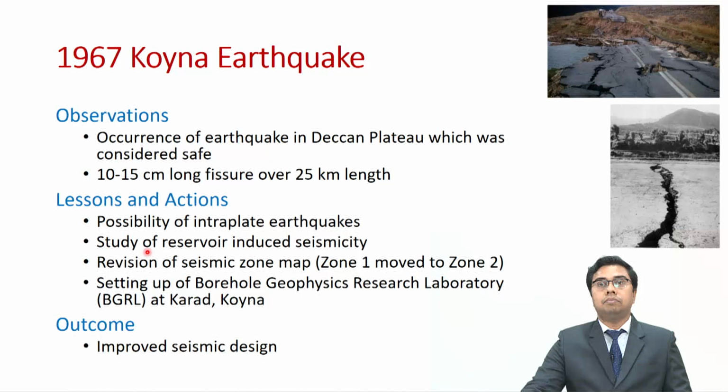This earthquake further propelled the study of reservoir induced seismicity, and there was a revision of the seismic zone map of India where regions in zone 1 were moved to zone 2, and the Borehole Geophysics Research Laboratory, BGRL, was established at Karad in Koyna to further look into the seismology of the region. And the major outcome of these lessons from the Koyna earthquake is that we have improved seismic design practice in our country.